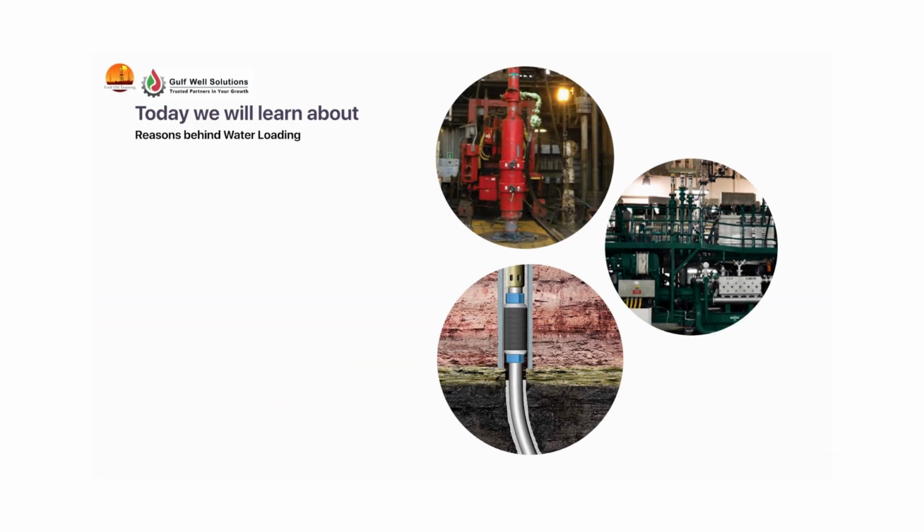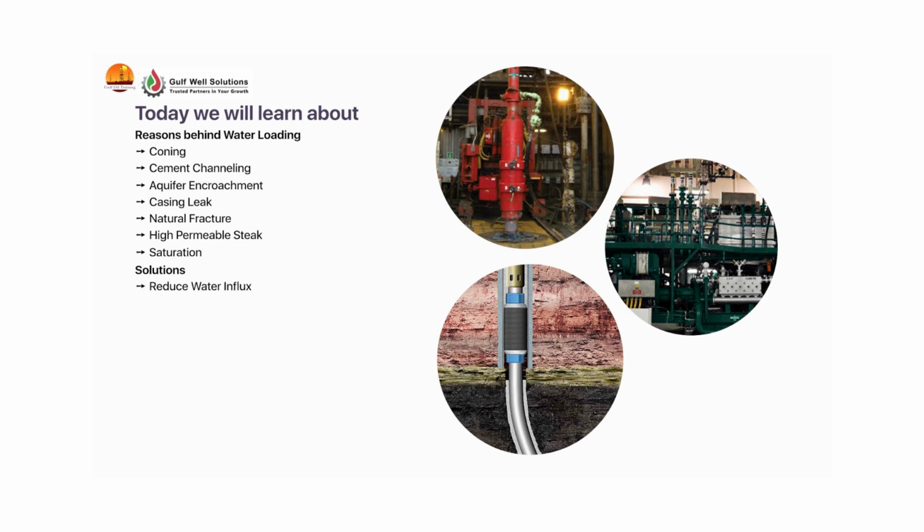Today we will learn about reasons behind water loading: coning, cement channeling, aquifer encroachment, casing leak, natural fracture, high permeable streak, saturation. Solutions: reduce water influx, lift gas and water together, surface water disposal, wellbore separation, lift water to surface separately.